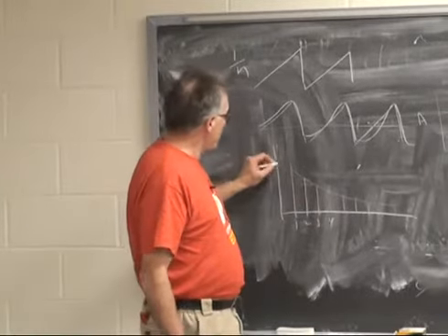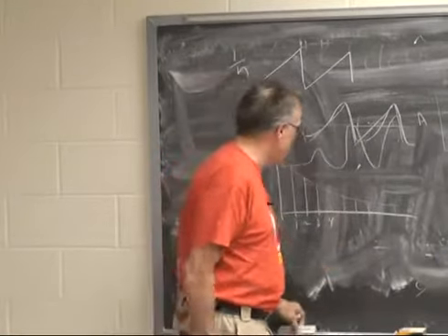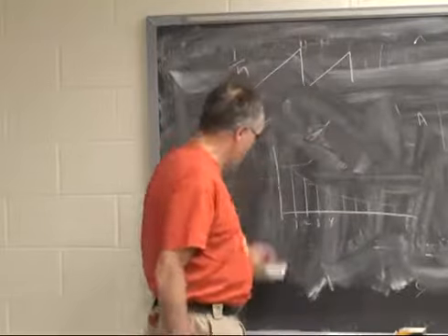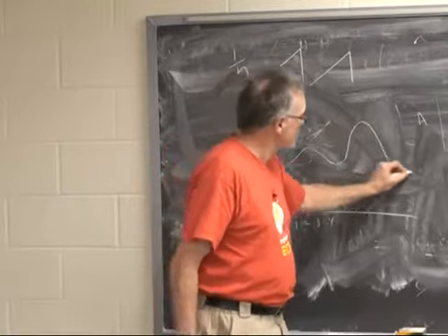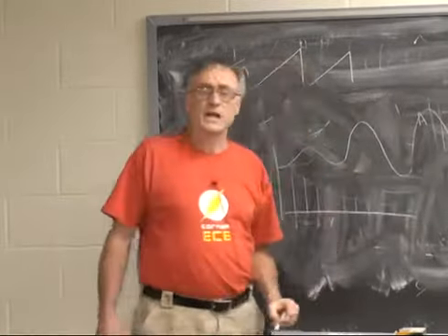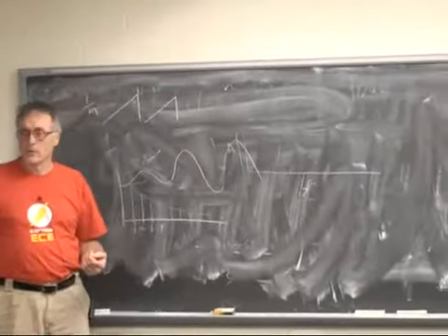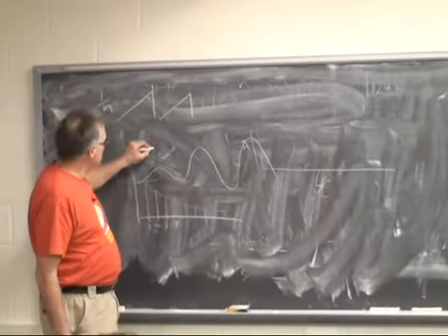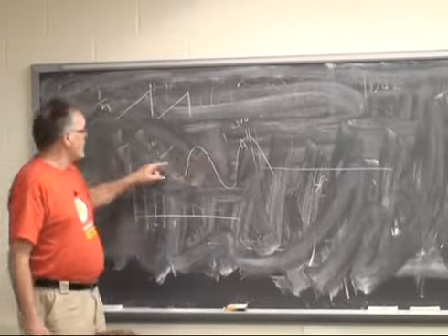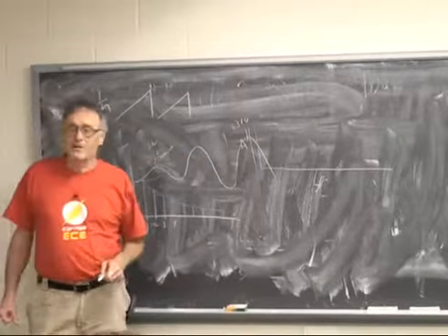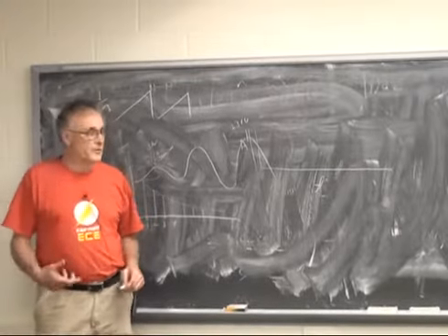That then is driving a resonance system that looks like, actually that's even too sharp. The resonances in frequency look more like this. And the top resonance can go as high as 3,000 hertz or so, but not usually that high, more like 2,300 or so. So the range of these resonances is from 300 to, say, 2,300. And there are typically 3 or 4 or 5 dominant resonances in everybody's speech. And these are referred to as formants.